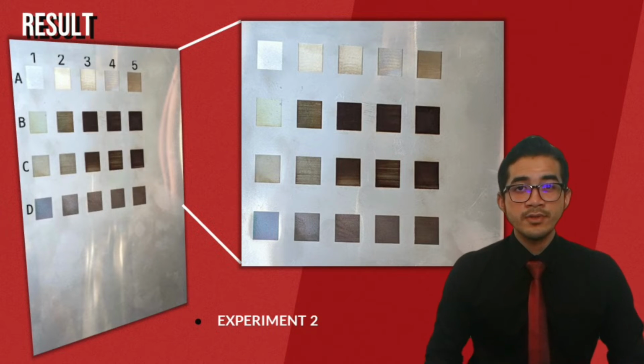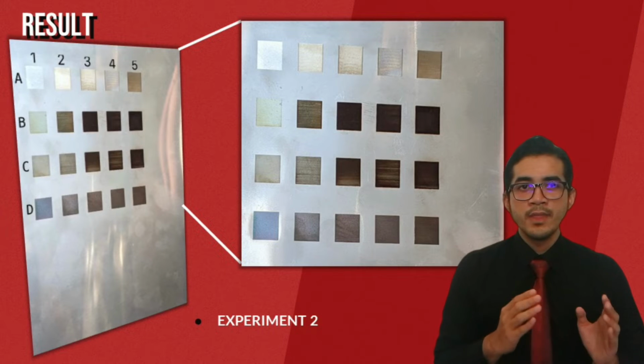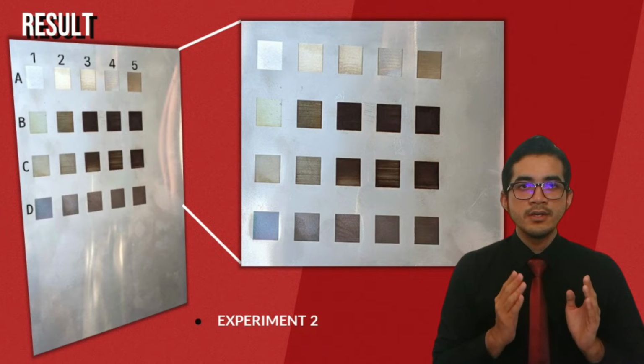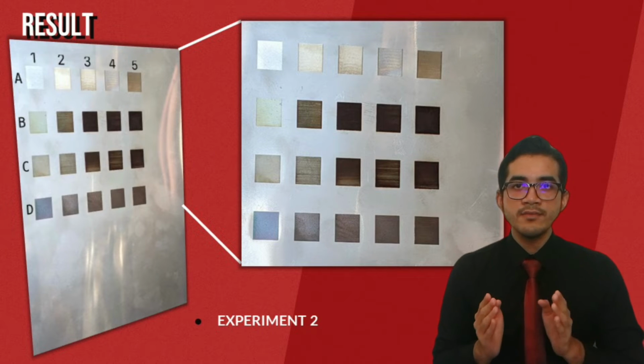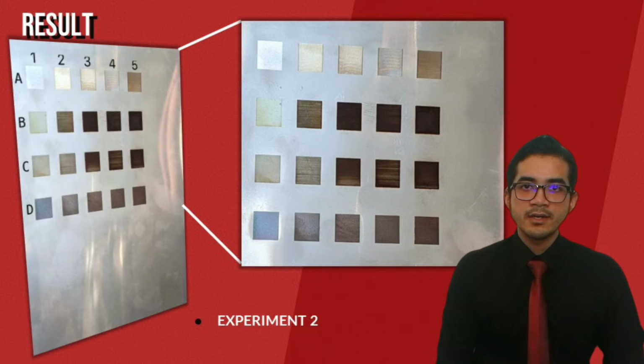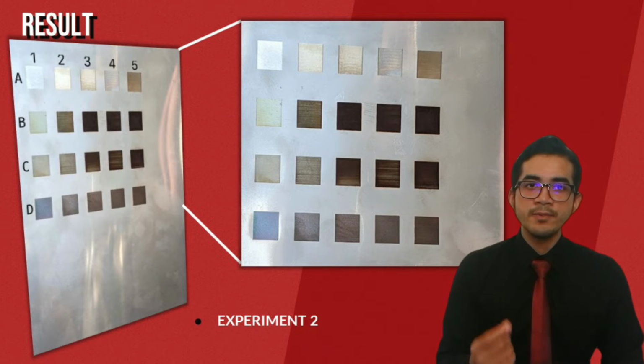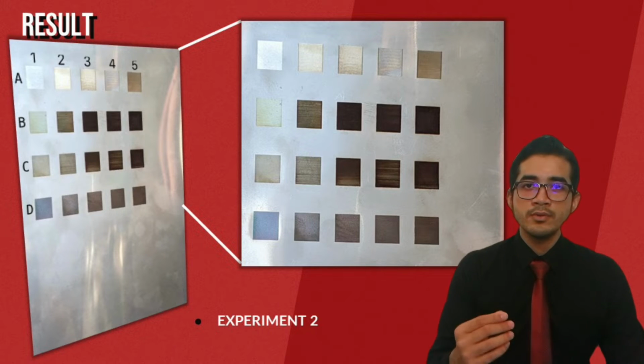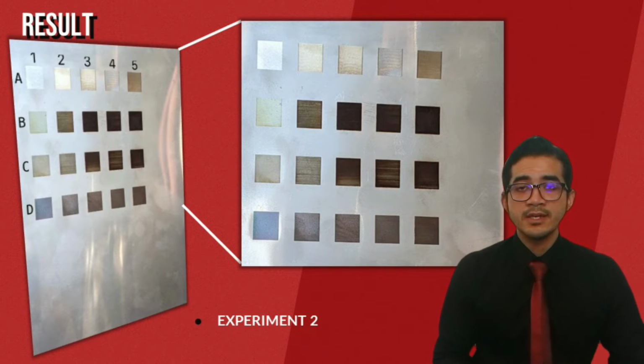In the normal vision observation, we can see that when the power is stepped up, the color of the engraved surface becomes darker, but the color also shows up in D1. So we are going to analyze it by the surface roughness value.